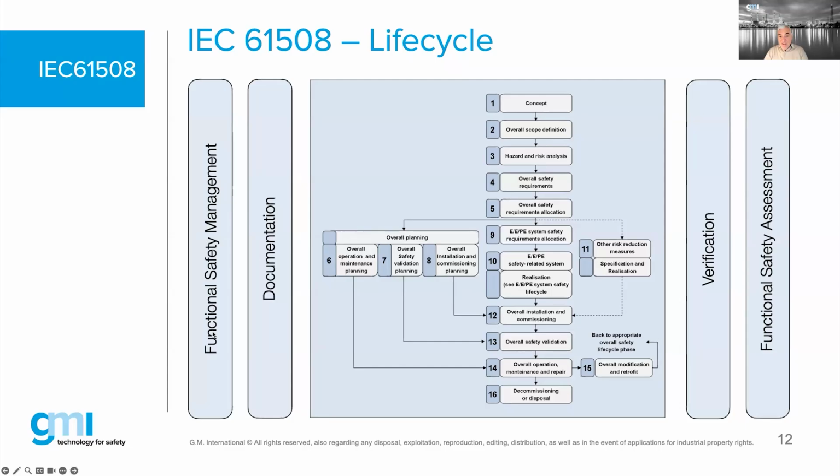And they do functional safety management here, which is actually a kind of quality management. As you have seen on the previous slide that Gabriele was mentioning, there was also a quality management system mentioned there. Well, the functional safety management specific to the manufacturer, when they are developing hardware and/or firmware, means they are following the 61508 quality management scheme, which is here called functional safety management.